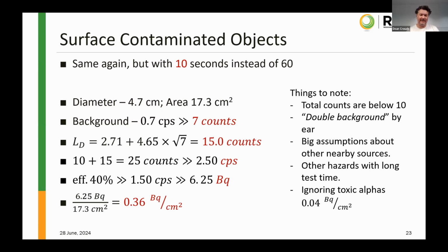And the last one is, of course, the radiotoxic alphas, which has got an even smaller limit. Generally, we don't see that in mining, right up until you talk about scrubbers, dealing with the off gas where they've got polonium. And that polonium-210 is considered radiotoxic, so it has a release limit of 0.04, which I am personally struggling to get something to be able to measure down to that in the field.